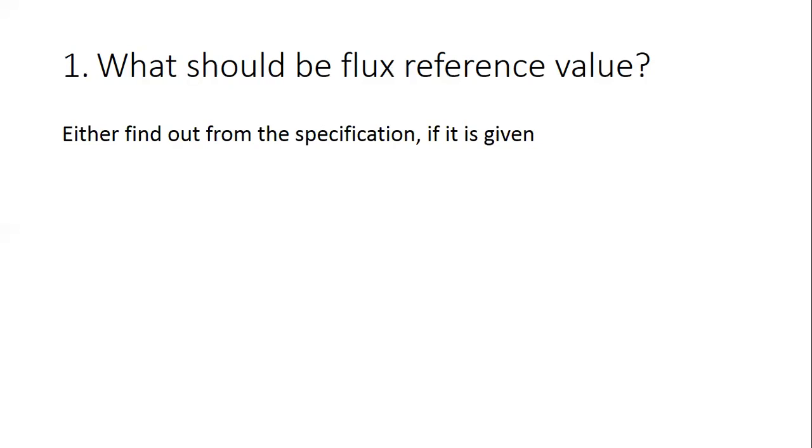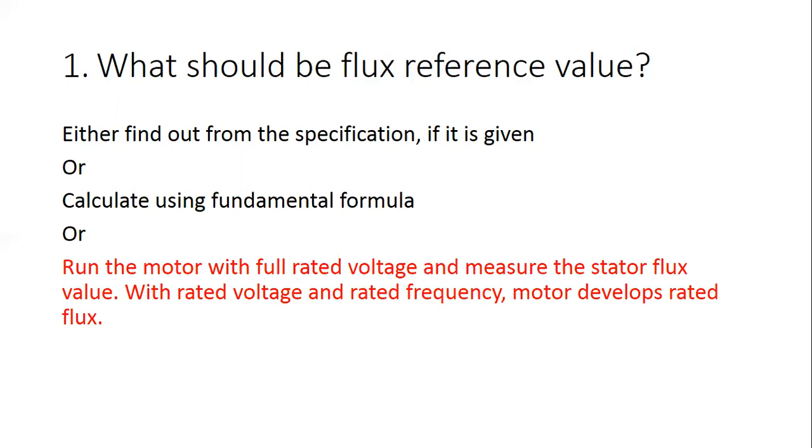Now the preset model which I have used in Matlab does not have the flux reference. One option is that I can calculate it using the fundamental formula, but I used a simple approach. I ran that induction motor with the rated voltage with all rated parameters, since measurements are possible in the simulation itself.